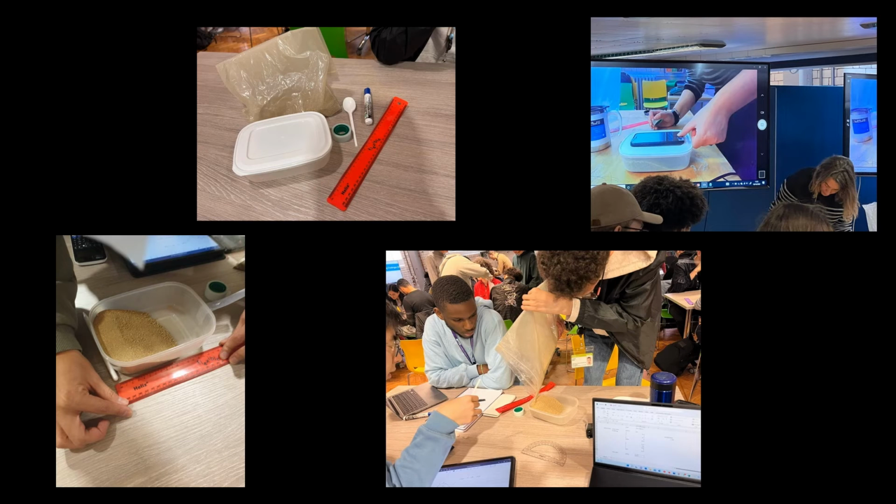In workshop 2, we create a 2D slope and measure the geometry by estimating the volume of the slope. Then by simply pushing the box to pretend the horizontal force applied by the earthquake, this allows us to see the change of inclination of the slope. Then we repeat the process 5 times, and plot the graph on Excel, which allows us to see the trend.